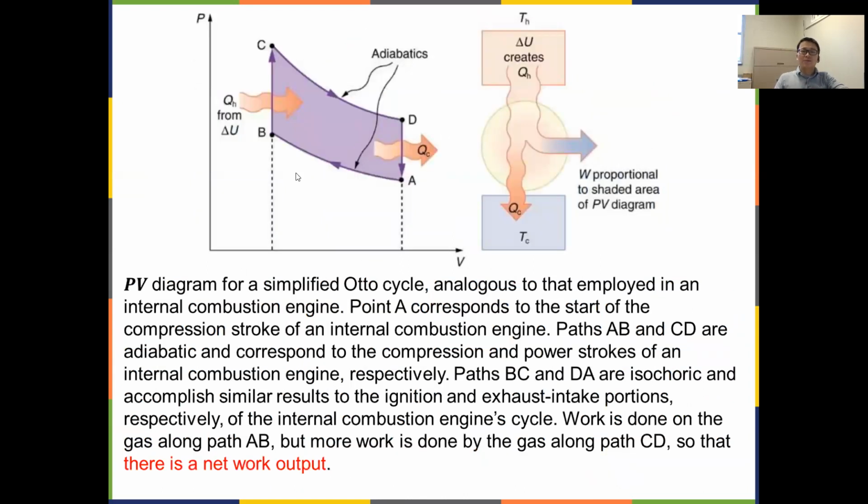So when that happens, if you look at the PV diagram, a PV diagram you can use to calculate what will be the work done by the gas system, and then to calculate the net work, and then compare to the Q takes in and Q takes out. Okay, so then we can calculate what the work output would be. A couple lectures back, we talked about using P times dV on the PV diagram to calculate the work done by the gas.